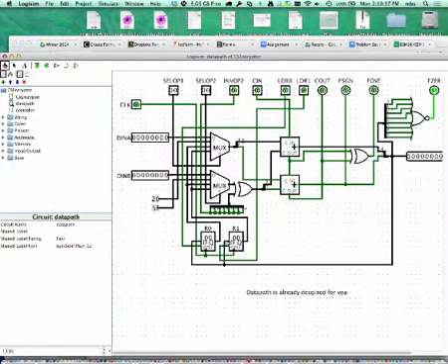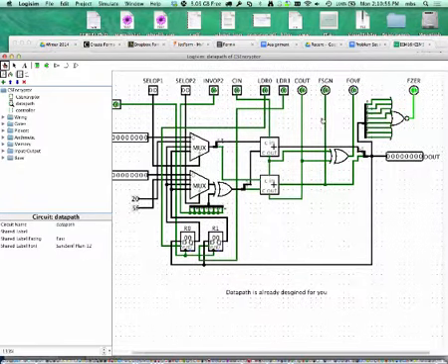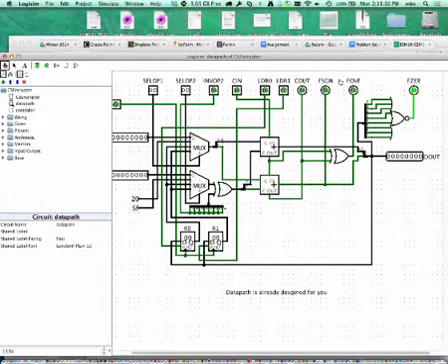So the load enabled signals for these two registers are brought out here, and your microcode has to control them. The output of the data path goes out into this line called dout. So whenever you're ready, your encrypted output will go out here. And then you have signals which tell you something about that value. So you can check whether the result of the adder output is a 0, is it negative?